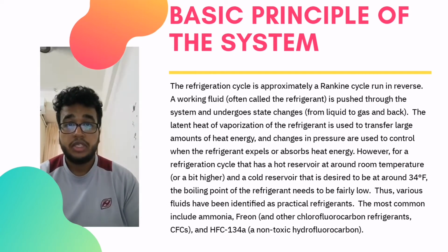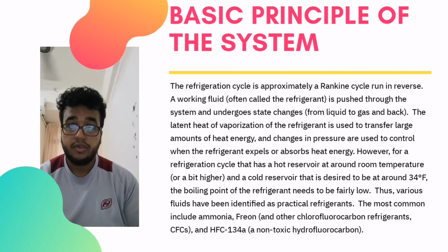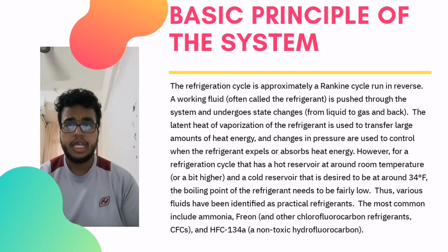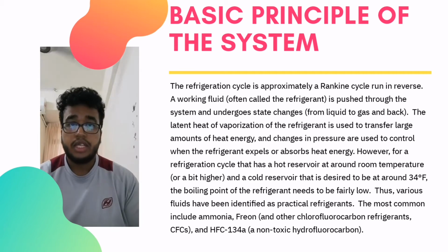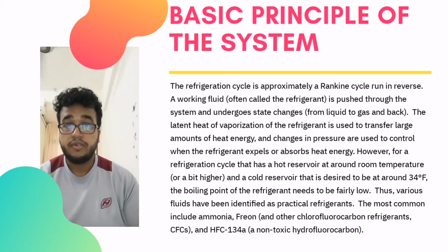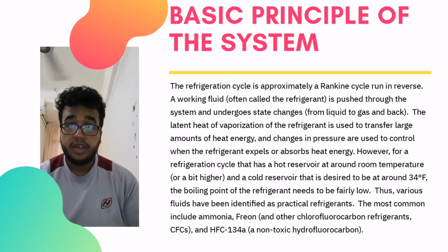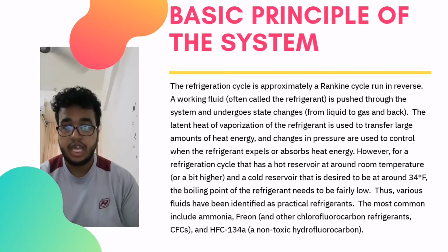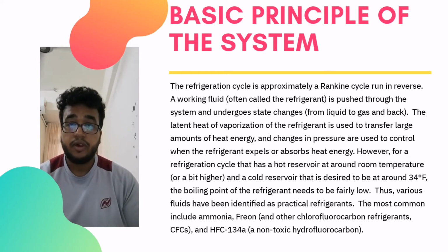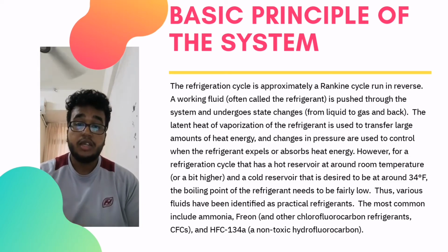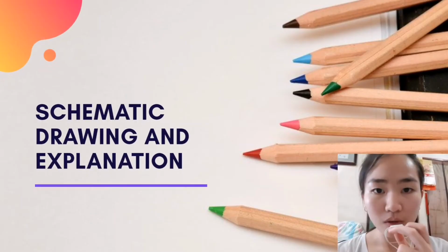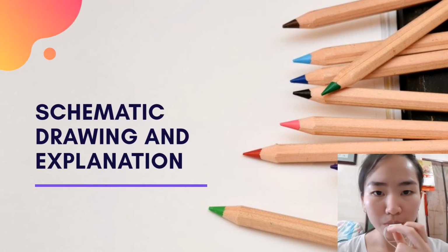However, for a refrigeration cycle that has a hot reservoir at around room temperature or a bit higher, and a cold reservoir that is desired to be around 34 degrees Fahrenheit, the boiling point of the refrigerant needs to be fairly low. Thus, various fluids have been identified as practical refrigerants. The most common include ammonia, freon and other chlorofluorocarbon refrigerants (CFC), and HFC 134A, a non-toxic hydrofluorocarbon.